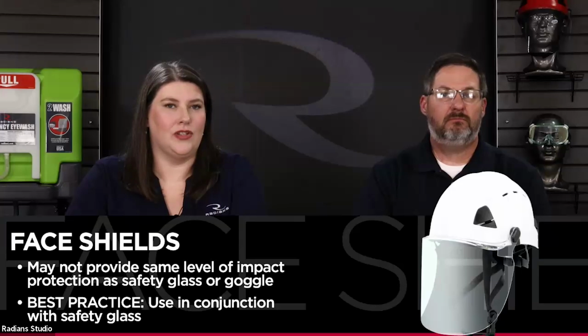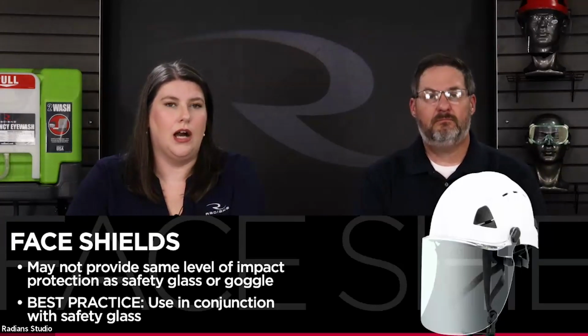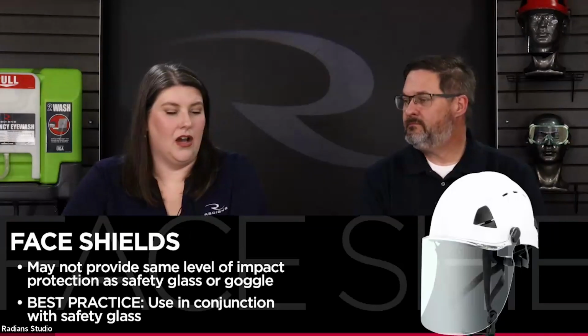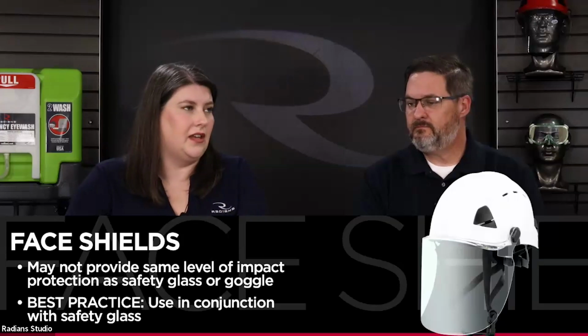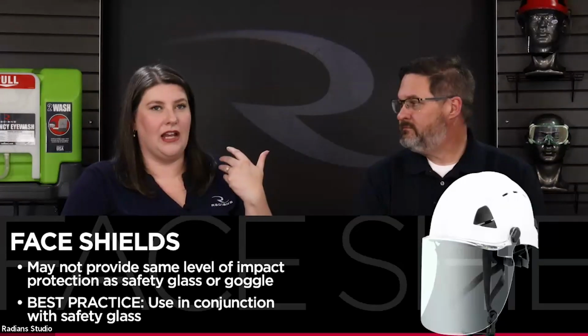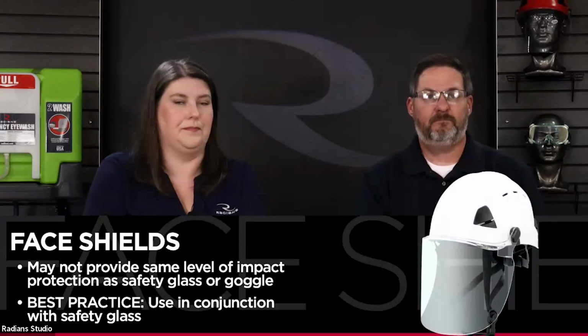And again, anytime you're using a face shield, you most likely need to still use a safety glass or goggle because say there's an impact that happens, blow off valve, something like that, that then hits your face shield. It's going to dislodge that. At least you still have your goggles, your glasses in place as an extra layer of protection there.